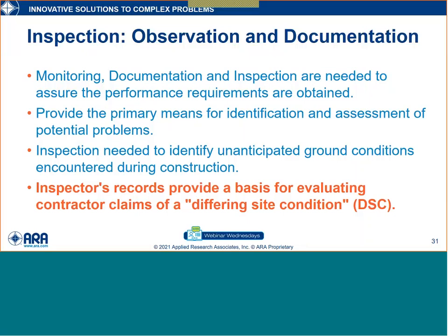So make sure that the specification correctly identifies the whole enchilada in terms of the basis of acceptance. Don't use exclusively non-destructive testing methods as a basis of acceptance. Frankly, that's wrong.